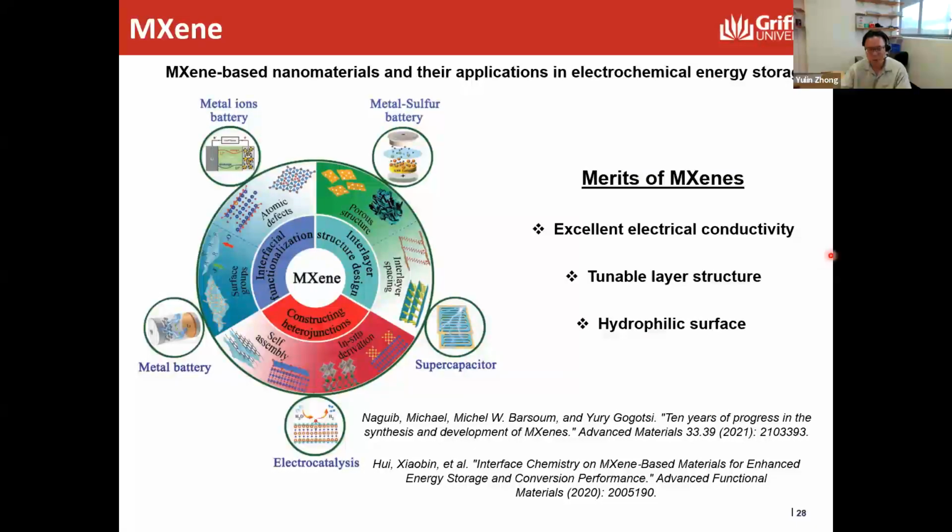But for MXene, what's so nice about it is that it can be oxidized, and yet it retains its electrical conductivity. Unlike graphene oxide, which is insulating in its oxidized form, MXene is still conductive in its oxidized form, so you don't have to reduce it, or go through a lot of trouble to make MXene conductive again. So that's, I think, the unique advantage of MXene.